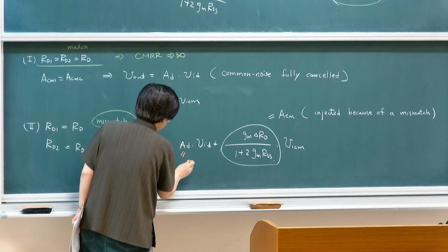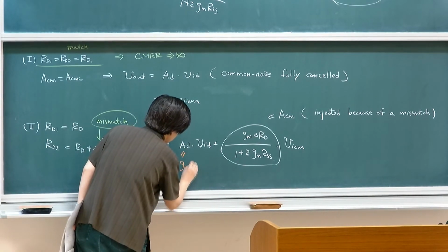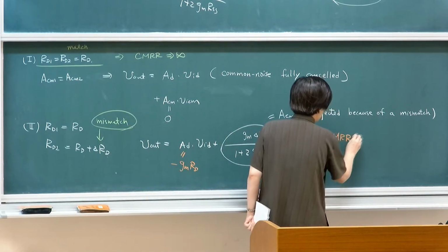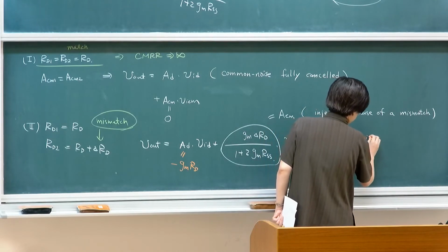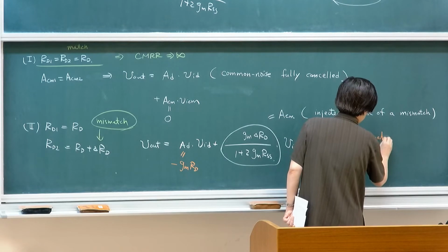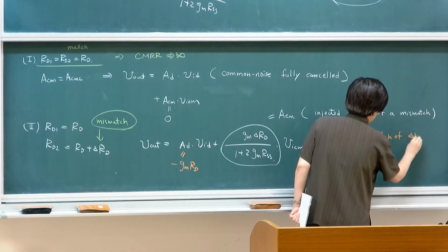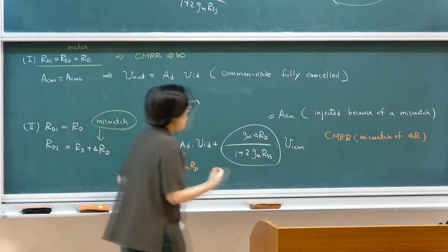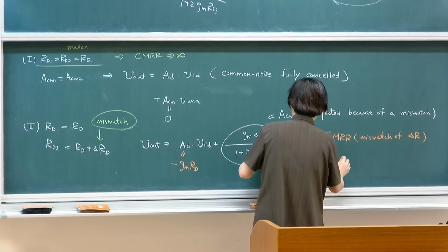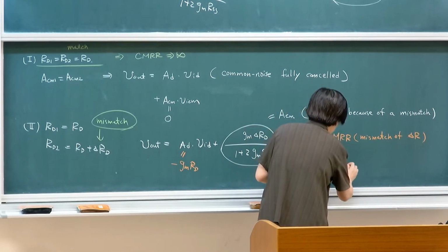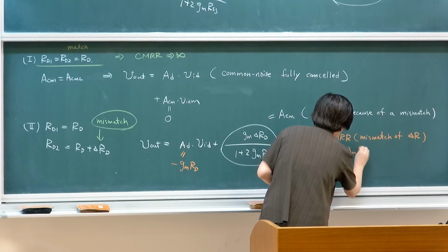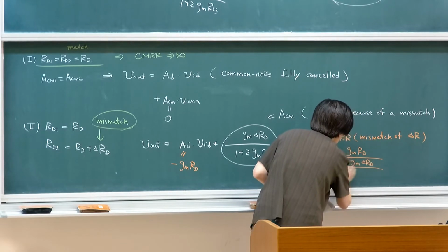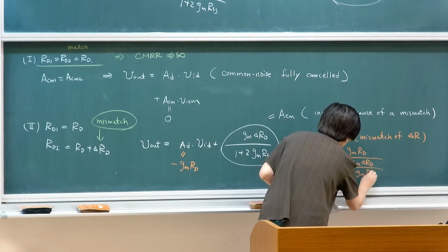We know that on the left, this is minus gm RD. So this is when there's a mismatch, delta R. Just to be clear, it's still fully differential, but there's a mismatch in your circuit, and this would lead to a CMRR which is gm RD divided by gm delta RD times (1 plus gm RSS).